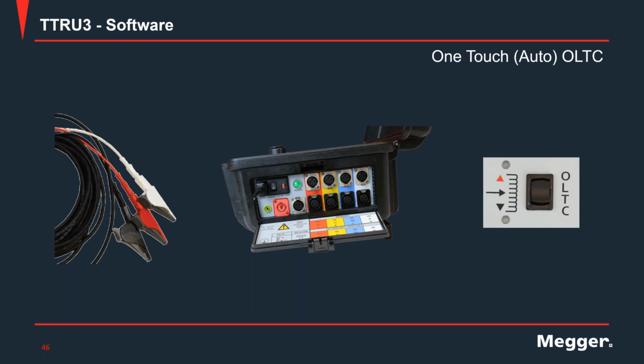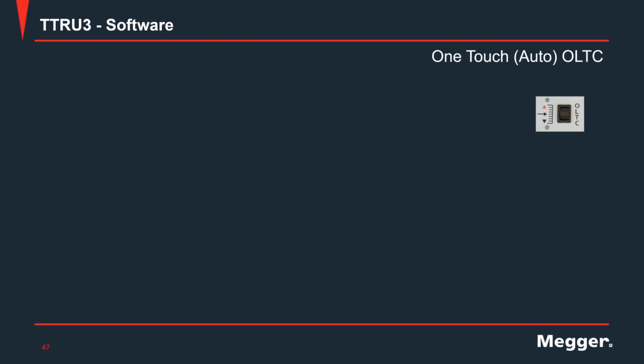Connect that to the control cabinet of your tap changer. Then on the top panel of the unit, we have the switch labeled as OLTC. As you see, you have a position to go up and a position to go down in your tap changer. So you have direct control of the tap changer from the unit. And better yet, those changes you can do obviously manually with the switch that I'm showing right now.